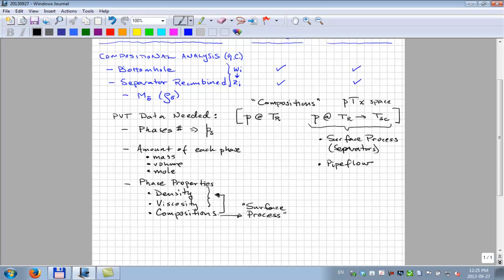The composition space being gas cap sample, a high up oil sample and a low down oil sample. Okay, so you normally capture this variation of PVT properties in terms of composition by doing a complete set of PVT experiments for several different fluids that have been collected from either the same well or various wells in the field. Okay? That's at least in the traditional sense of the word. So basically when we want this pressure, temperature, composition space covered, this is by doing the set of experiments that we're going to talk about for multiple samples that have been collected.